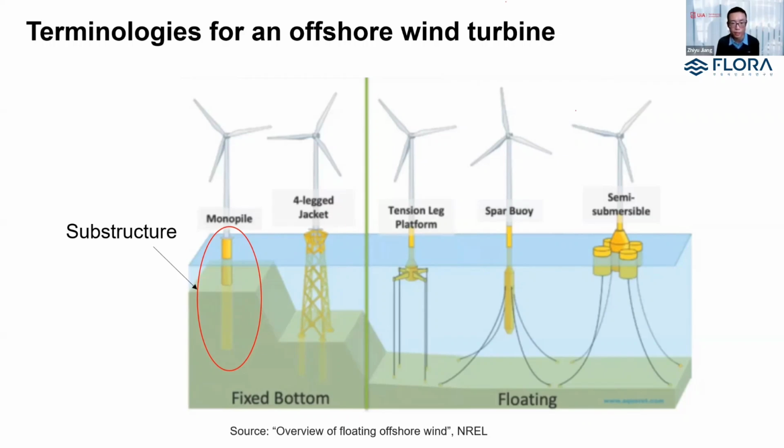As you can see here, tension leg platforms have vertical tendons that provide large pre-tensions. It is these vertical tendons that make the system very stiff and prevent it from having large offsets when subjected to wind and wave loads. That's a unique feature of tension leg platforms. But also, because of the large pretension of those tendons, the mooring and anchoring costs can be prohibitive. That's why there are very few commercial projects on tension leg platforms.